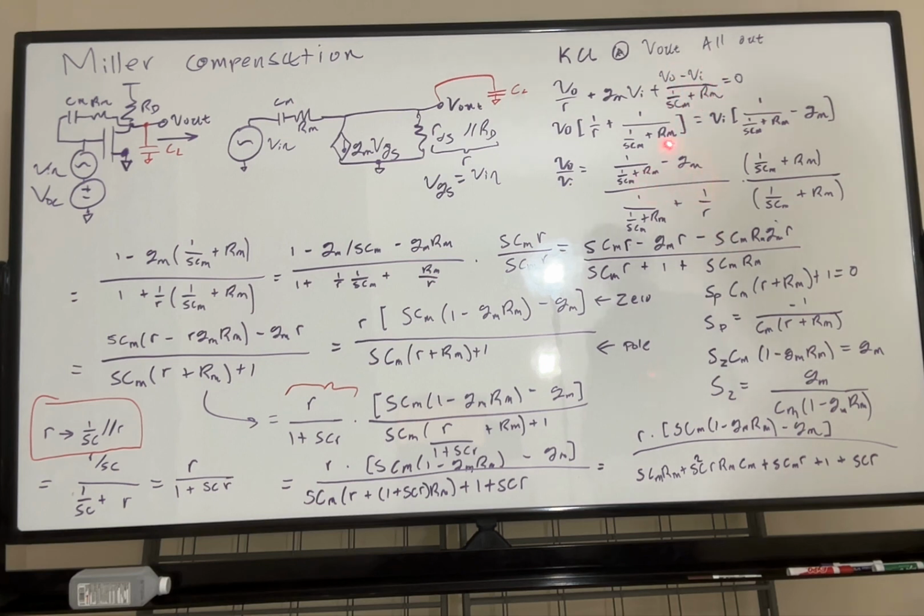Oh, and we're going to ignore all the parasitic capacitors in the circuit, because if you had to include that, it would make this a bit more annoying, because then you'd have a CGD in parallel with all that, and, forget that. We don't want to go there. Okay, so this is the term of the current going from the output to the input, like this, right?